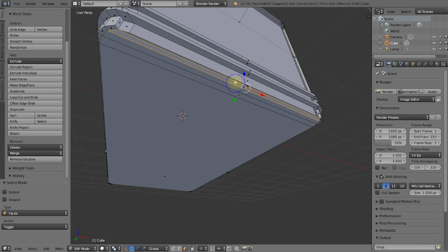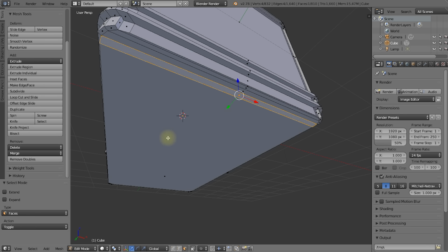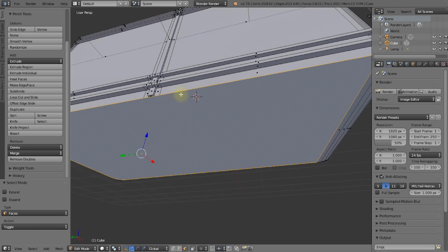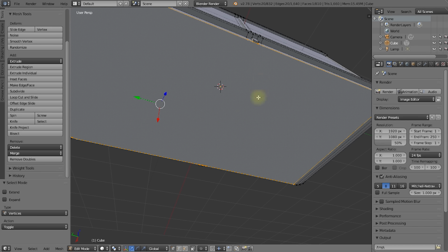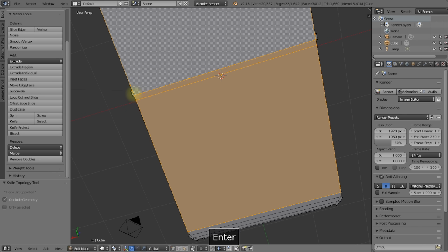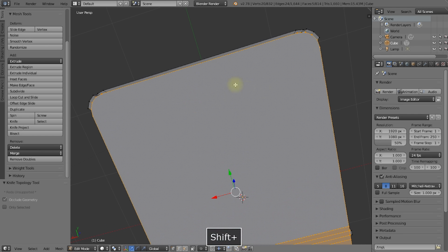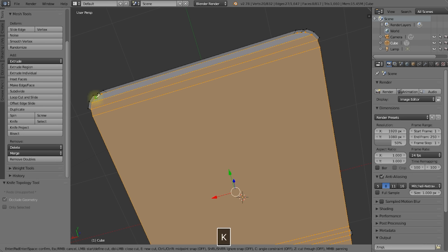I'm essentially creating these quads, these faces that have exactly 4 vertices. As I said, this bottom one is still an n-gon, so we still need to create all of these individual cuts. I'm just going to speed through this, but I'm really just repeating this process of cutting between matching vertices on either side of my mesh. Just make sure you are cutting between the correct vertices.